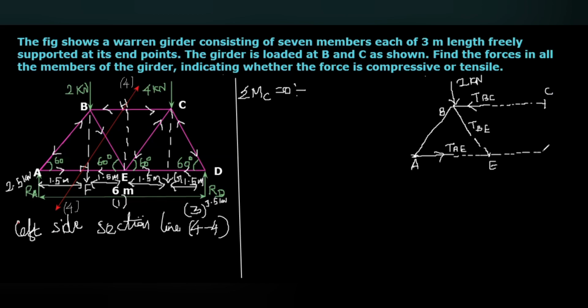From the point E, this one, that is CG. So with respect to the point C, we are going to calculate the moment. Here you can see the RA at point A, an upward force, is also acting. So when you take moment about C, we can consider this RA is acting along this line and it is exactly upward.